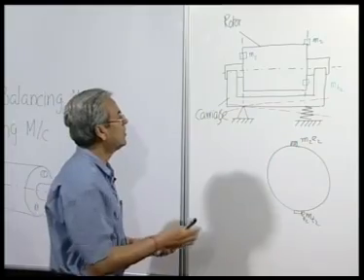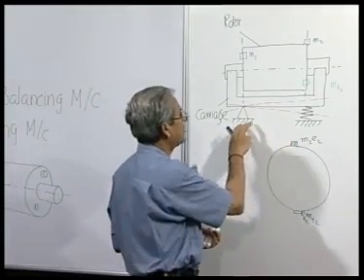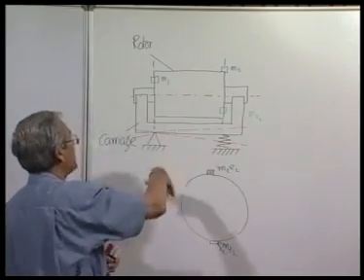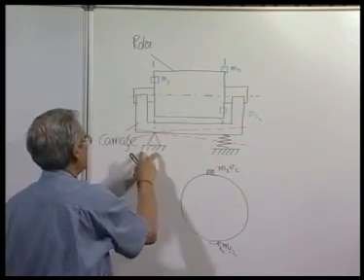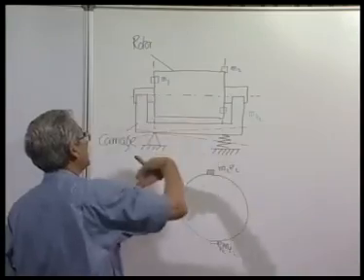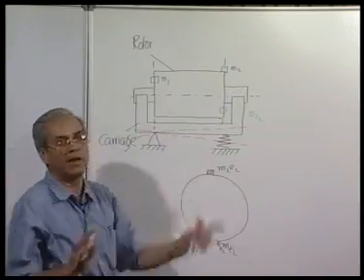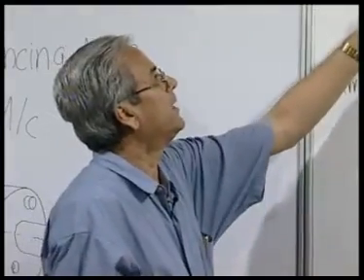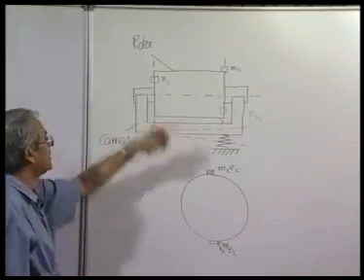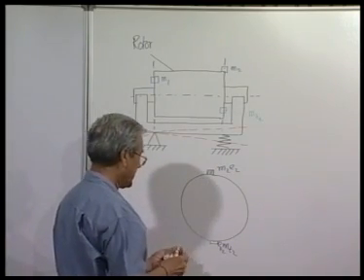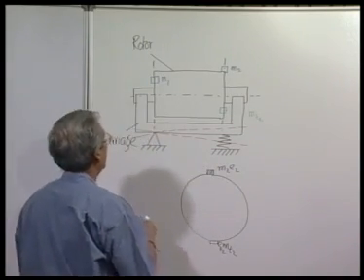Next what we do, we just shift this pivot to the other balancing plane 2, and then what will happen, the oscillation and the spring is shifted here. So, when it is rotated, then the unbalance which is created by m 2 will be having no effect, and unbalance created by m 1 is going to have the effect, and we follow the same procedure in placing one balancing mass on this plane.